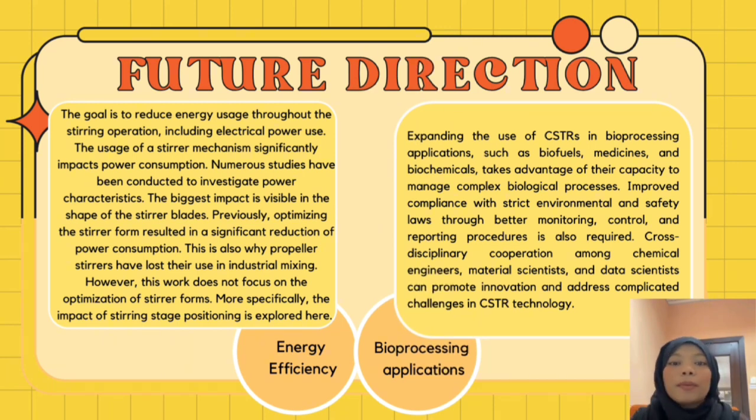process. Lastly, bioprocessing applications. The bioprocessing industry has made extensive use of CSTRs because of their capacity to offer effective mixing and ideal interaction between the waste stream and the biomass. These reactors are especially useful for digesting high-strength organic waste produced by food processing, brewing, the dairy industry, among other industries. One of the main benefits of CSTRs is their low construction cost and straightforward design, which make them an affordable wastewater treatment option. In order to maximize the effectiveness of the bioprocessing reaction, optimal heat and material distribution are ensured via thorough mixing within the reactor.